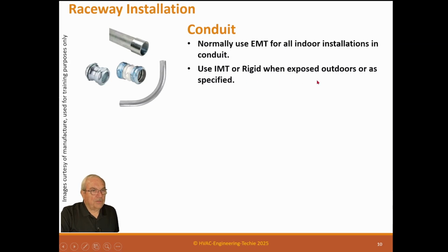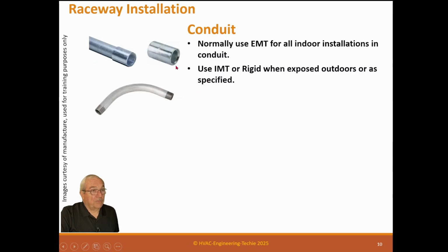Use EMT or rigid when exposed outdoors or as specified. So IMC is intermediate conduit, and it's a little thicker than EMT, but not as thick as rigid. And they use connectors that are watertight, basically, and are used for EMT. This is an EMT connector. And rigid looks like water pipe. It's not. It's conduit, but it uses threaded connectors just like a pipe. And your elbows are bent threaded pipe. So this is very thick conduit and is normally done for exterior exposed to weather.